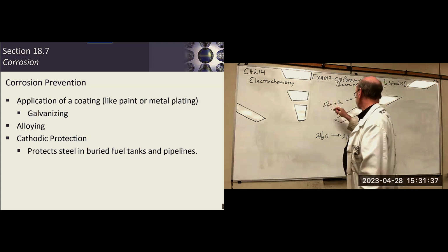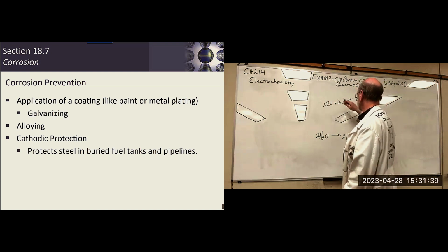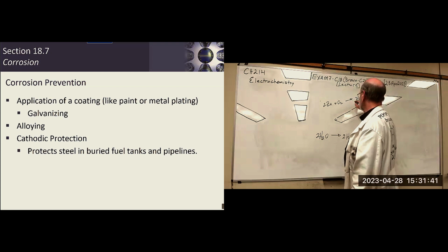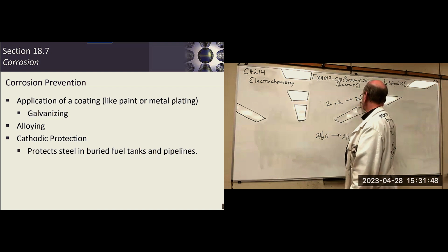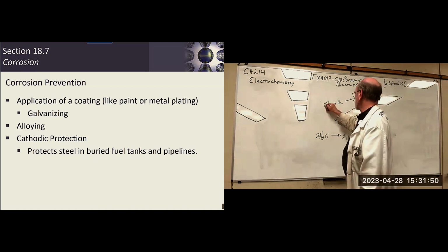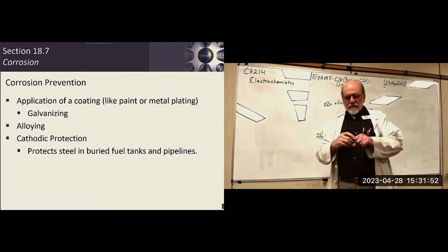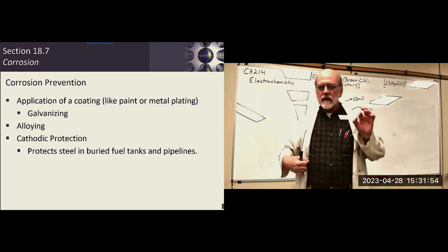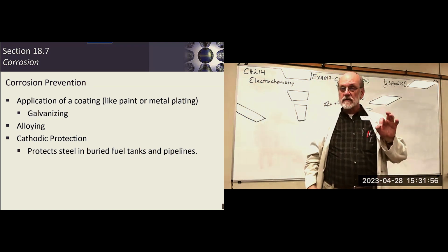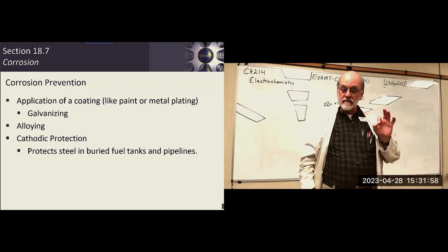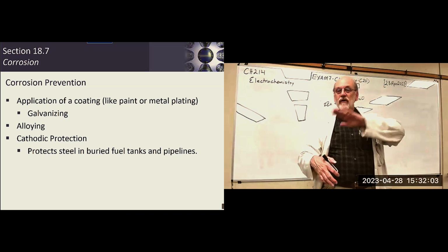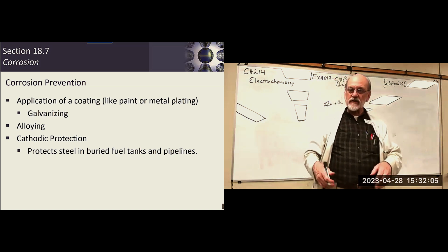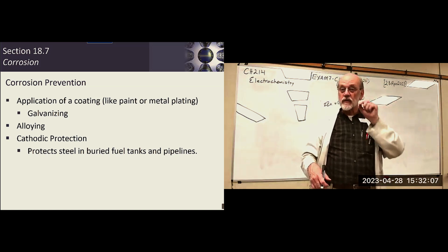All right. Let's see. Need 2 here. Yeah, 2 here. And it corrodes much faster and more readily than the iron underneath, the steel underneath, and it creates an oxide layer on the surface. So it prevents any oxygen from getting through even to the rest of the zinc.